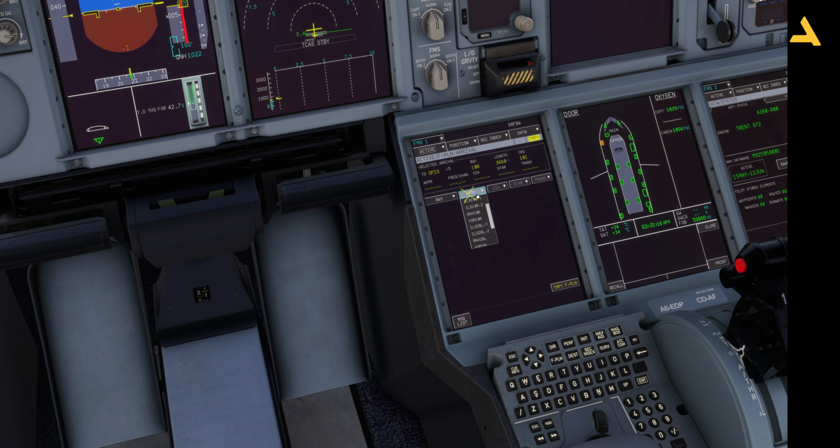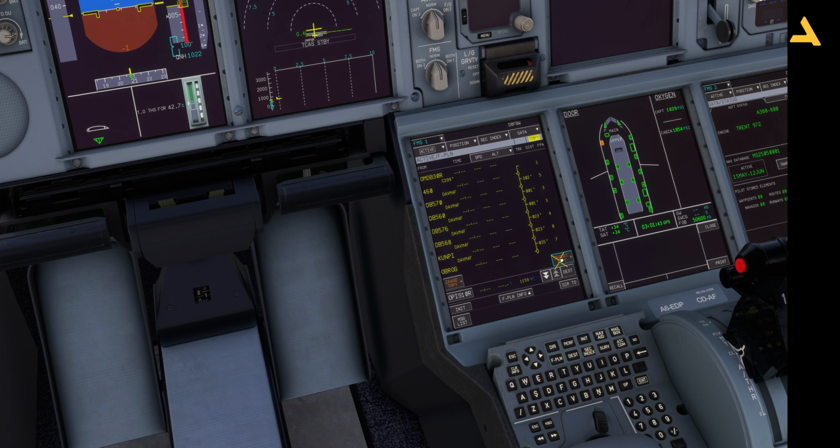Right, approach, ILS. Then you can select different approaches, whether you want to go for RNAV or VOR or ILS. So this is ILS 10, right? This one. Now via, I will just select none. I will show you why I've selected none. And the STAR is Kalmi 1A. And press temporary flight plan. That's it.